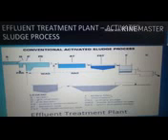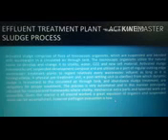In the conventional activated sludge process, there is a screen and grit chamber, a pre-aerator, primary sedimentation, aeration tanks, a final sedimentation tank, and there is a tertiary filter and chlorination, primary sludge, waste activated sludge and returned activated sludge. In ETP, the activated sludge process comprises floc-forming microorganisms which are suspended and mixed with wastewater in an aeration tank.